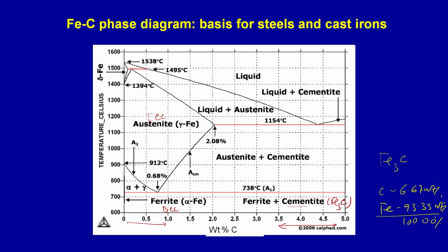And these steels are basically based on the classic iron carbon phase diagram. I will not discuss these aspects because that will take a lot of time, but for you to know that the basis of steels and cast iron is this diagram which you are seeing on your screen now. This is nothing but pure iron in which carbon is added. A small amount of carbon is added, varying from 0 to about 6.6 weight% carbon.